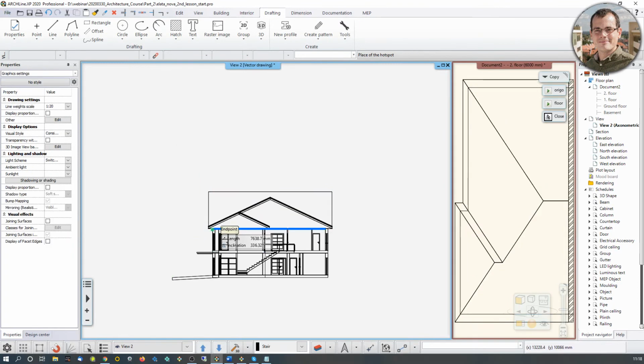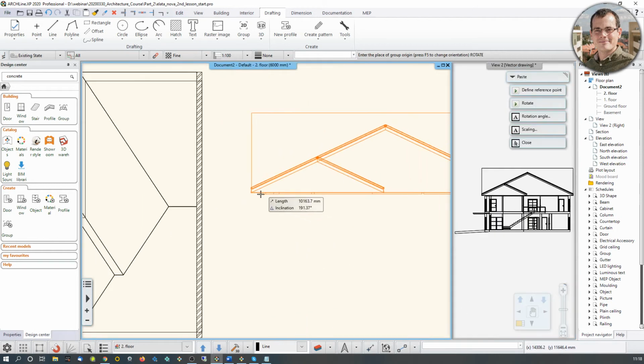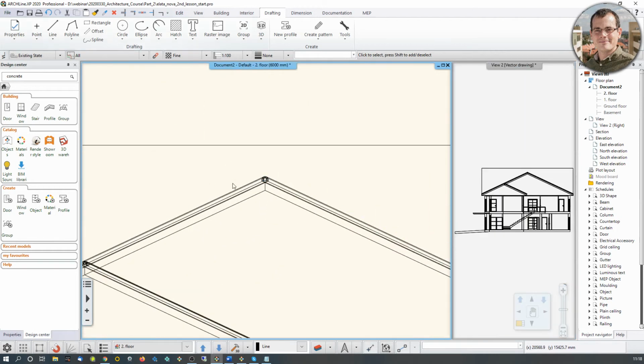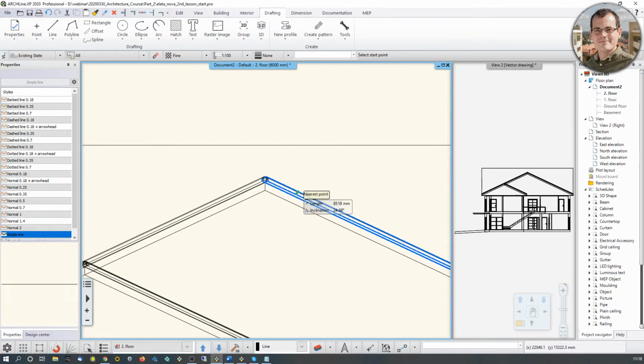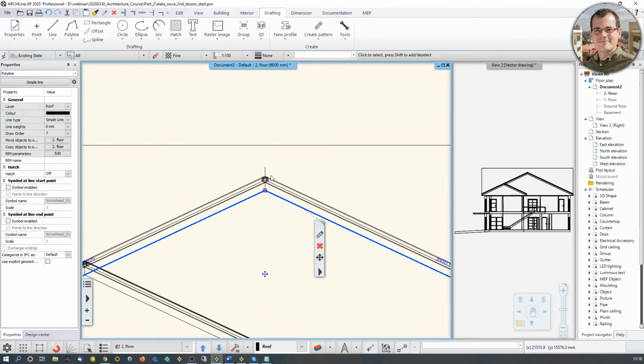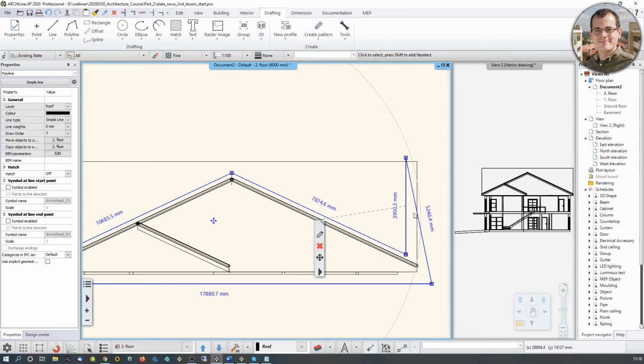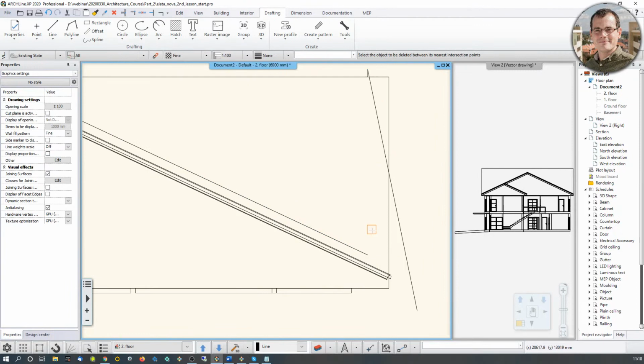So Ctrl+C, go to the 2D, paste down the drawing, and now what we did before, we're just going to go line 500, and selecting this line I can offset it upwards, offset all, offset it. Now the problem is that now I have this kind of extra nodes that I don't really need, and I can amend that with this very handy tool, delete between points. Just click the lines that you don't need and they are going to be deleted.